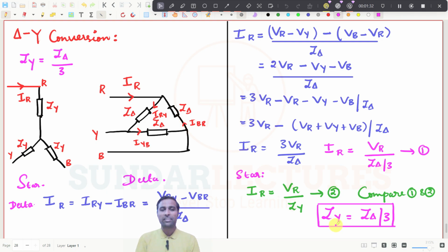That is the application of these things. It comes under three-phase motors. They always start with the star connection and then go to the delta connection. So many things are there, the application of star-delta starters. Everything comes under this basis. Anyhow, the star connected impedance is equal to the delta connected impedance divided by 3, or delta connected impedances are 3 times the star connected impedances.